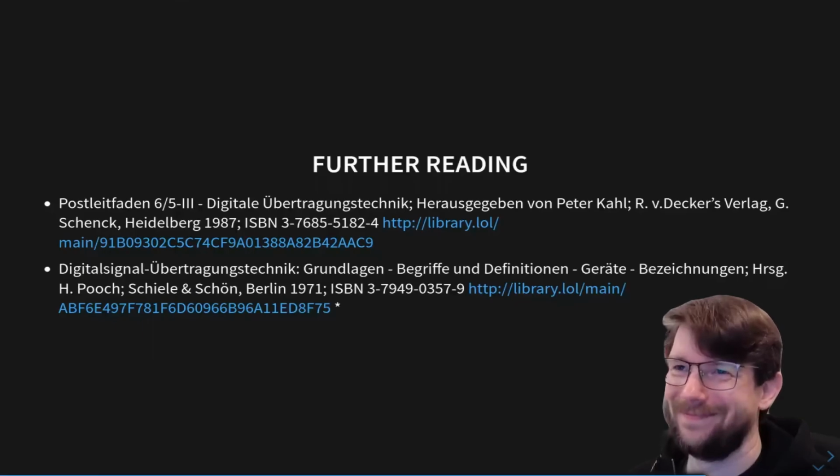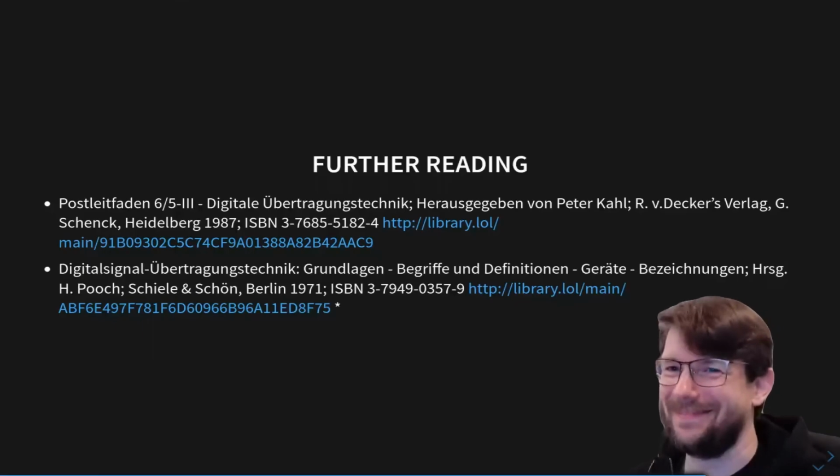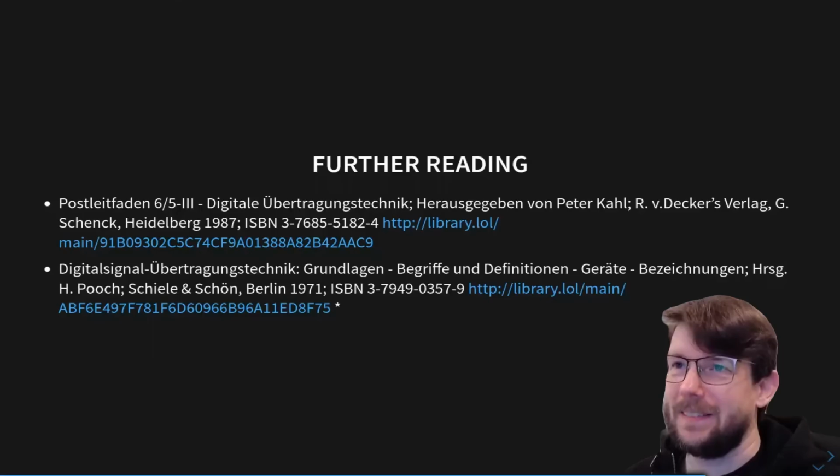So at some point, depending if it runs slightly fast or slightly slow, we'll need not to send the nominal 8 frames, but either 7 or 9 to compensate the slow drift that you have between the computer clock and the actual E1 clock. That's why there is 7 or 9. Yes, and it makes the story with the alignment slightly more difficult, but just slightly, I would say. Or I had the impression when reading it.